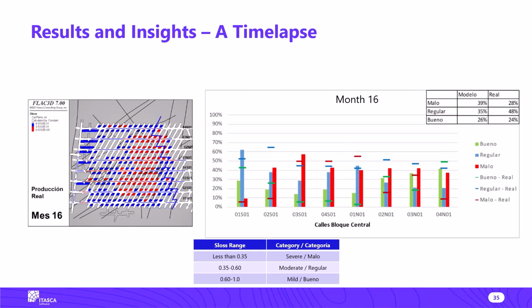This is now month 16, and collapses appear in the stress shadow. Those on the west end don't seem to be related to the mine front, hence we suggested that they were likely caused by irregular drawing. That means that stagnant sectors in the cave will accumulate stresses which will overload the pillars.